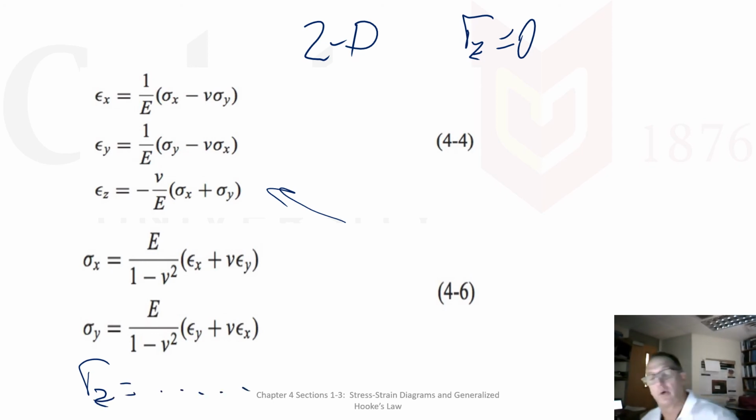So this is equivalent to being on the surface of an object where I'm not imposing a normal or a tension or a compression force on anything. Once I'm on the inside of a structure, then I'm always going to have something pulling or pushing on me in all 3 directions because of Poisson's ratio. That is, once I pull in the X, the material has to shrink, and so it pulls the material next to it. So there's those internal stresses. So that's what we've got.